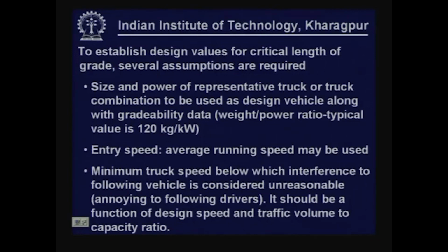A typical value is maybe 120 kg per kilowatt. So, we have to specify the size and power of the representative truck or truck combination we are trying to use as design vehicle, and the gradability data, particularly weight power ratio, becomes critical.